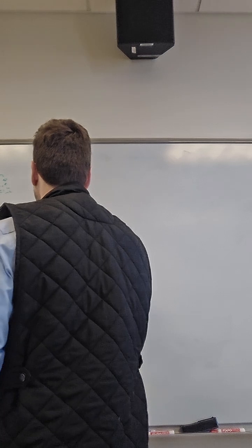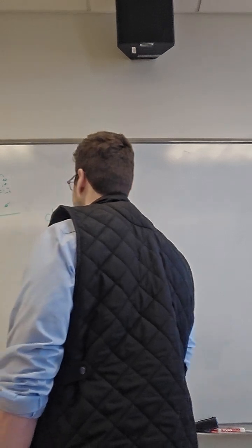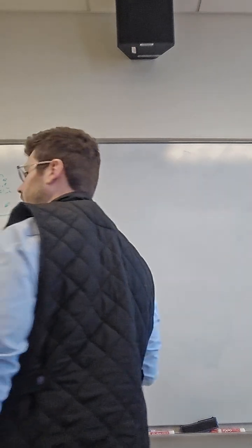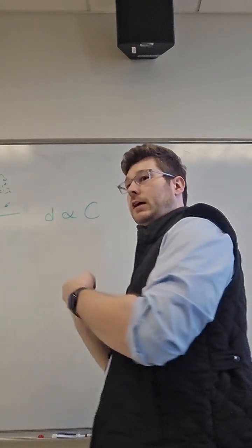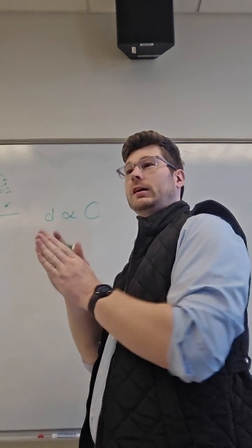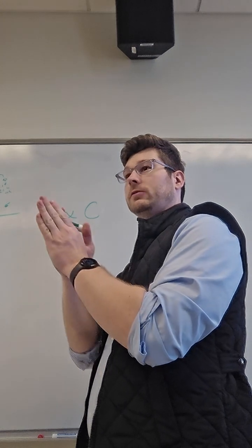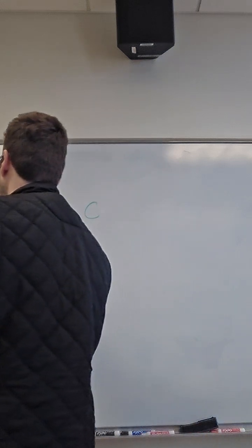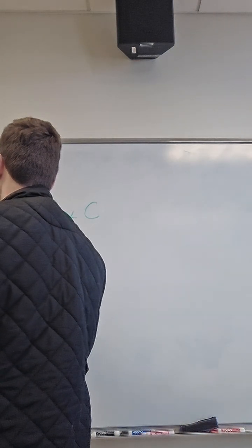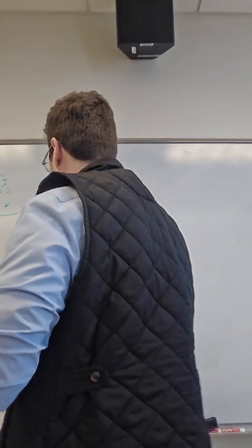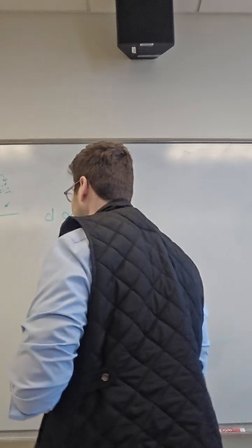All right, 2 things scale with capacitance. Distance is related to capacitance. The closer these plates get, as they get infinitely closer together, the capacitance starts going up. When 2 plates are farther away, the capacitance goes down. Same deal if you misalign the plates. It's all kind of like relative surface area. If you misalign the plates, the capacitance will go down too, because less charge can see each other, right? The distance that the electric field has to cross is greater. So distance and capacitance are related.